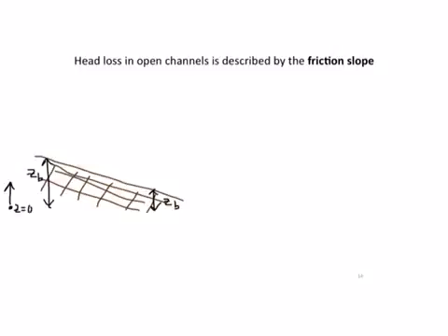So there's our elevation head component of the Bernoulli equation, and then we have a pressure head that's due to hydrostatic pressure. Hydrostatic pressure, remember, rho gh, is determined by the depth of the river. So the second term in the Bernoulli equation, the pressure head, is equal to total pressure, or rho gh. Remember, P equals rho gh. But the second term of the Bernoulli equation is P over rho g, and so the rho g's cancel out, and what we end up with for this second term is just h. So we have our river depth upstream, our river depth downstream,